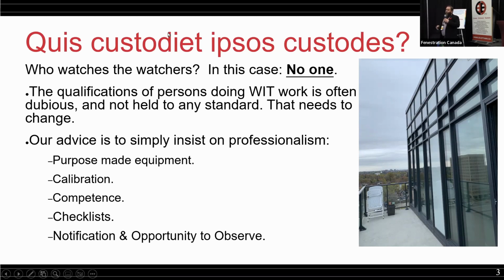So there are standards, of course, that apply to the work. The E1105 is how the test is actually done. The pressures to which the test is done is specified by code under A440. The Canadian supplementary gives you a lot of information and gets specific about what pressure at what height in a given geographical location has to be applied. But at the end of the day, if the architect or engineer decides that they want to test the window up to the full maximum spec of the window that the manufacturer said, it just becomes a big fight.